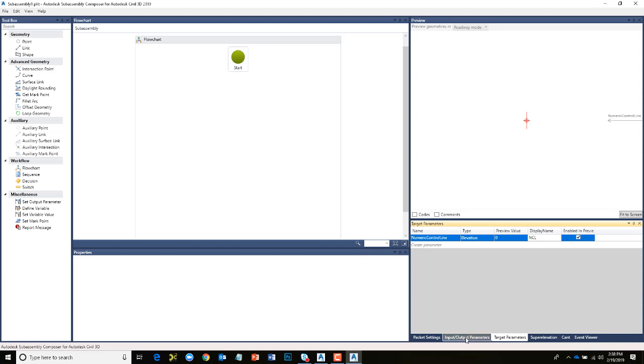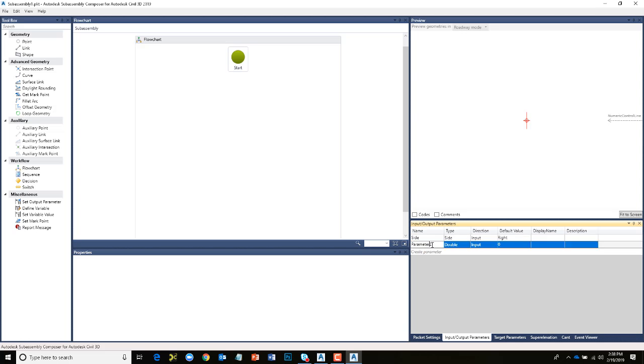All right, one more thing. I need to create an output parameter because I want this to be the number that it comes up with. I need to pass that to another subassembly dimension. So we're going to create an output parameter, and as long as we're on this tab, let's set the default value for the subassembly part. I'm going to set that to right. So this way, each time we drop this in brand new, it's going to want to go by default to the right side.